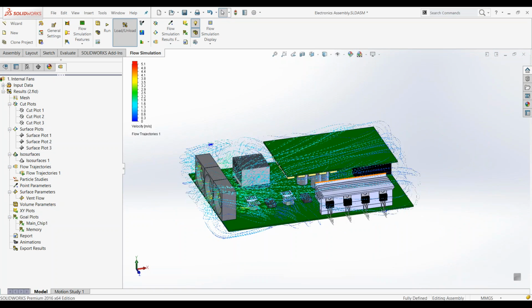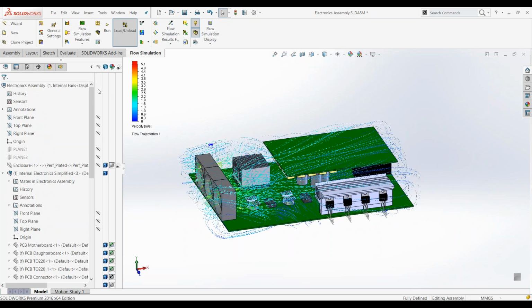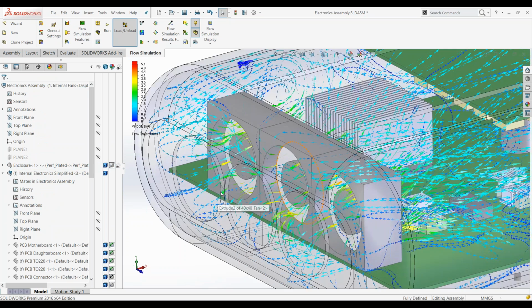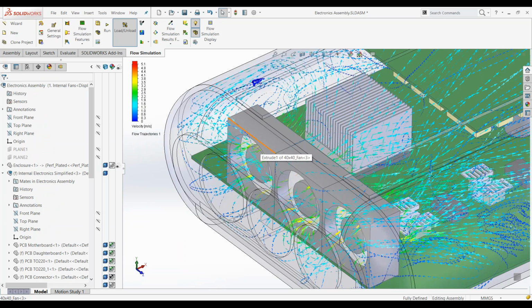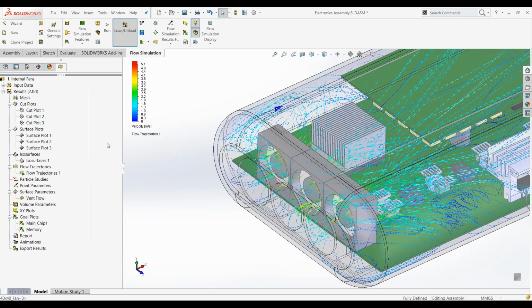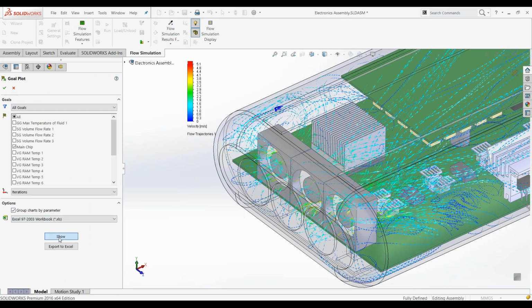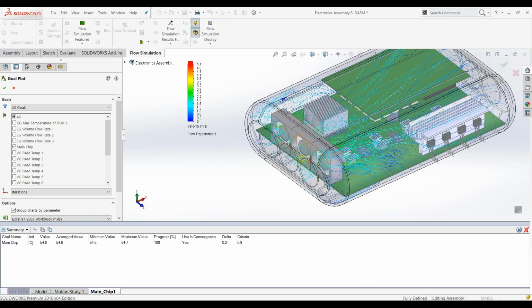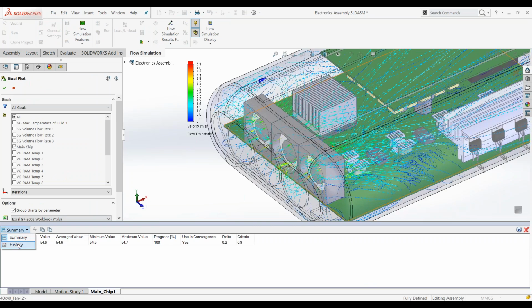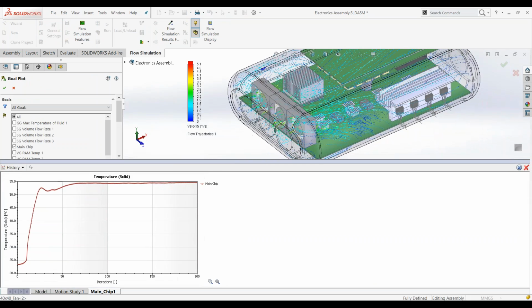away from the casings, from the top slot holes and from the perforations on the end and the front to capture fresh air from outside. That's how it goes. Okay, so we might want to look into the results on what the temperatures are on the main chips, which are under the heat sinks. If you look at it, this is how the temperature builds up and eventually reaches 55 degrees C during the steady state.